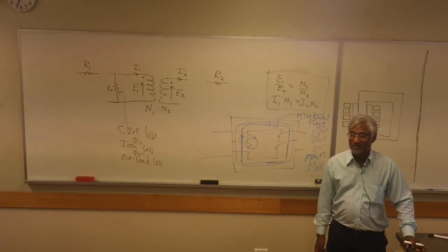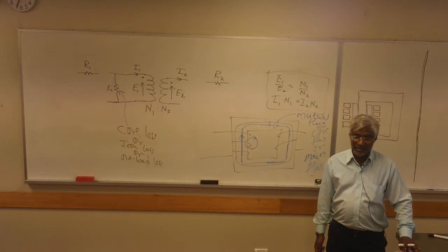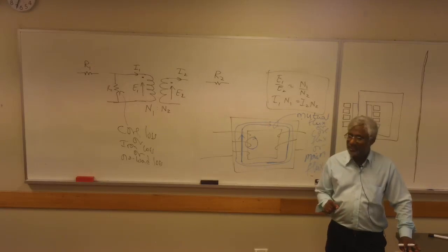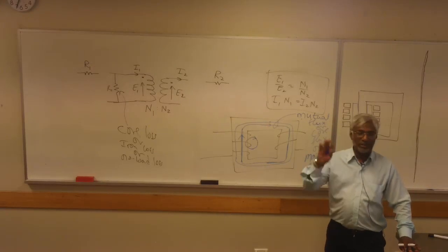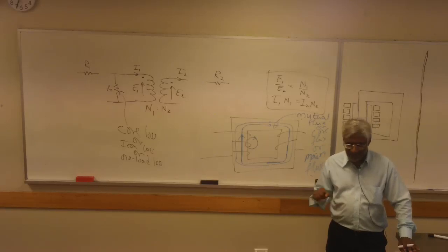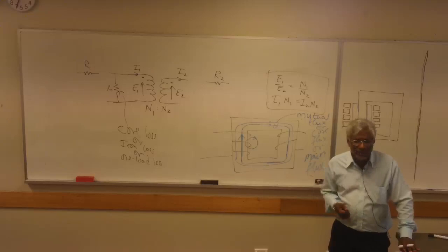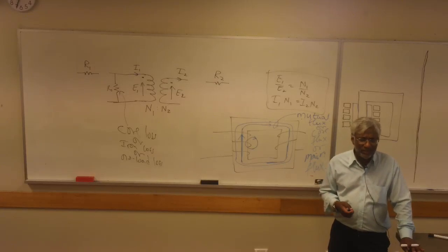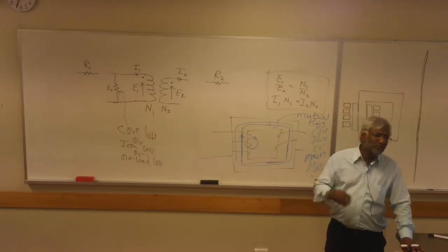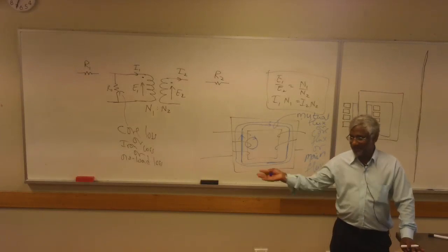About 1,000 times, if the iron has a reasonable amount of flux in there. Of course, if it has very, very little flux, then it would be more than 1,000, about 5,000. As you put flux in, the iron becomes a bit less permeable. And then there is a point where the permeability will suddenly drop and become as bad as air.